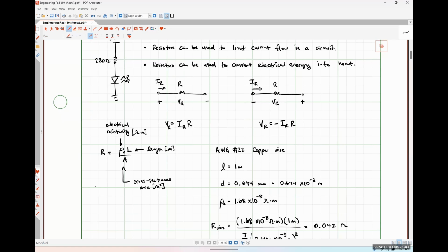Since it's a real wire, it does have some resistance. It will have some real amount of current flowing through it. And so the voltage drop across that wire can be large enough to cause your equipment to operate incorrectly. So out in practice, as electrical engineers, interns, and stuff like that, wire resistance might matter. In this class, it definitely will not. Okay, so I just want to make you aware of that.